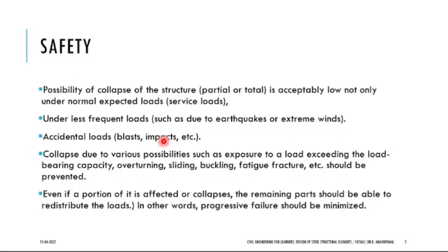And the other thing is the place where you will have a mining area. If you are constructing a cement factory, the cement factory will be constructed only on the slope of the hills where you have the raw materials, yes or no? You will have limestone in a particular hill or mountain, and there you will have the cement factory. You will extract the limestone by blasting, yes or no? Without blasting you cannot get the limestone. When you are constructing a cement factory, you should take care that the impact due to the blast is considered when your structure is being built.